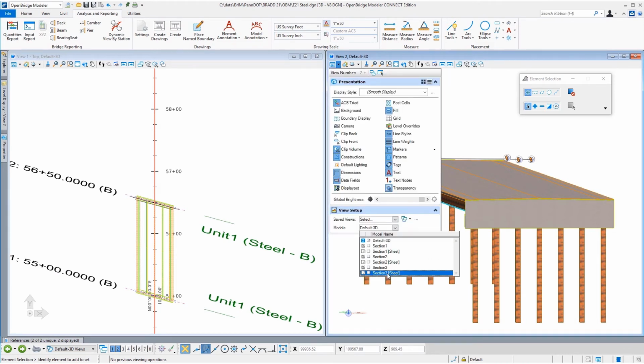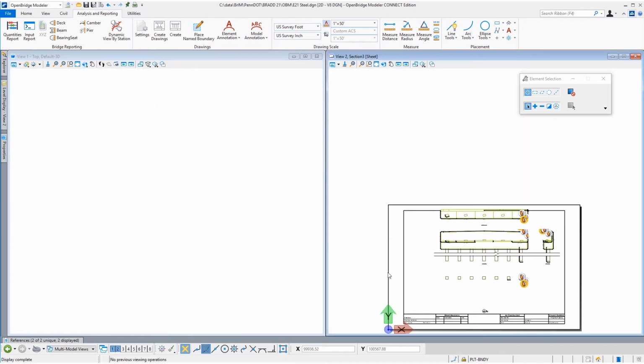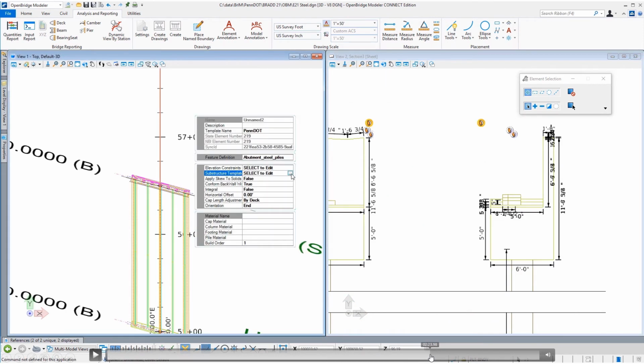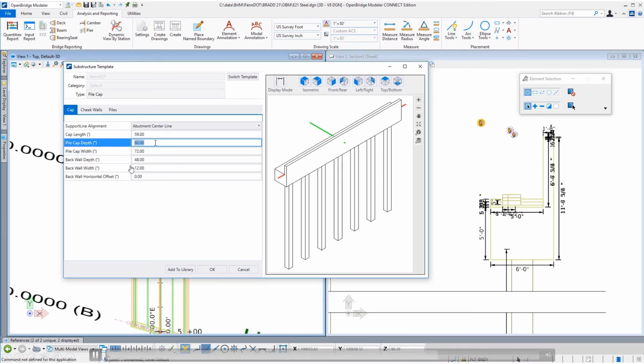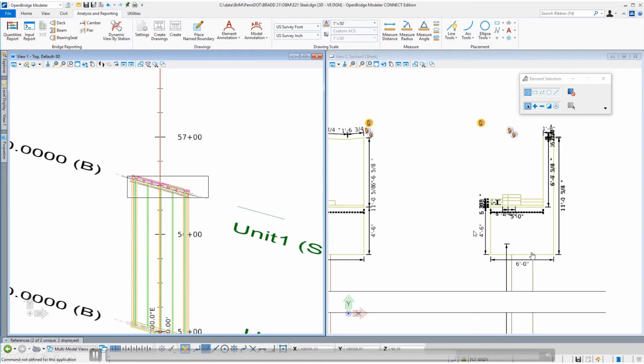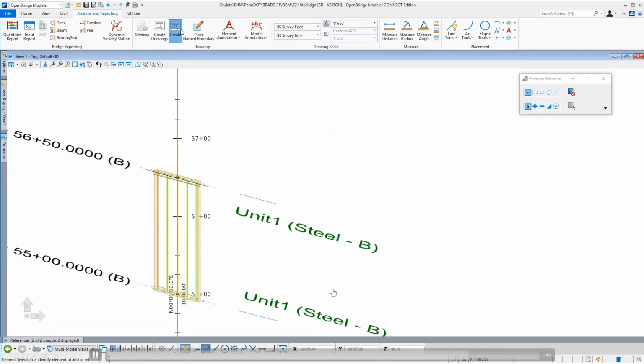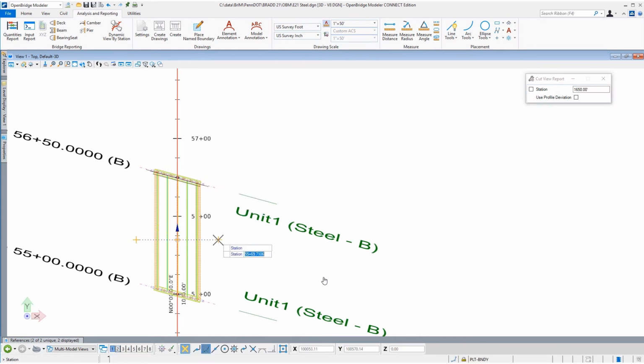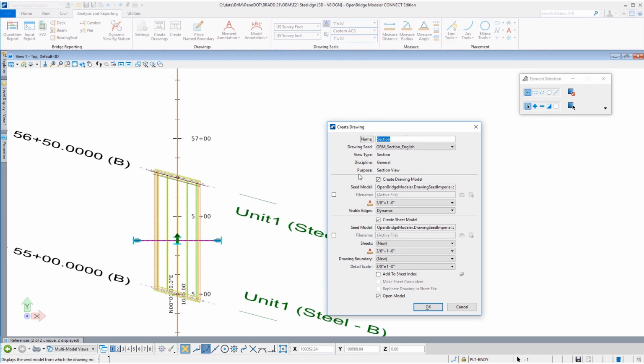Now, what is the next step on that? So you can also do the sheets, right? And adjust it and move it. And if you change anything on the abutment itself, for example, I would change the dimension here, right? Your sheet is not static. Your sheet will change. As you select it, these are reference files. You see how it changed? These are reference files or a different view of that 3D model in anything you can change, right? So that's the advantage again of being model centric, that all of these cuts are not static ones, they are dynamic cuts. Well, that's their name, dynamic views.